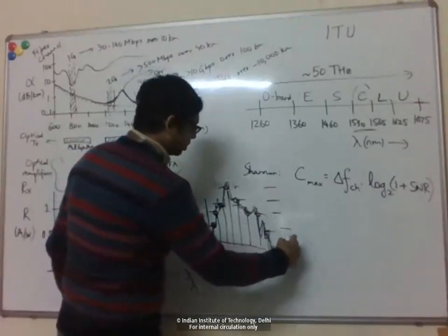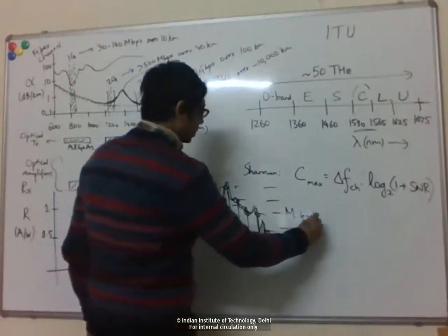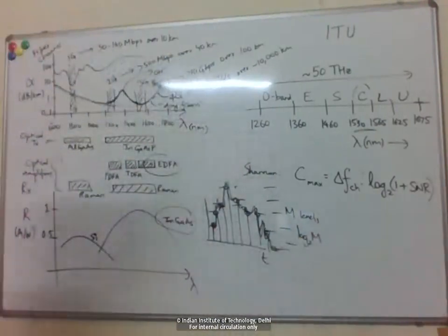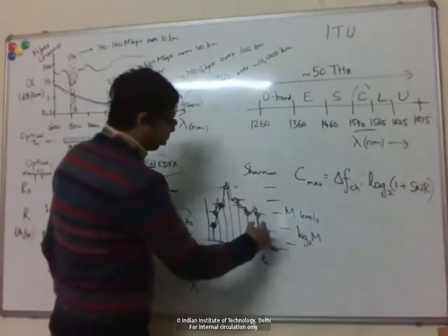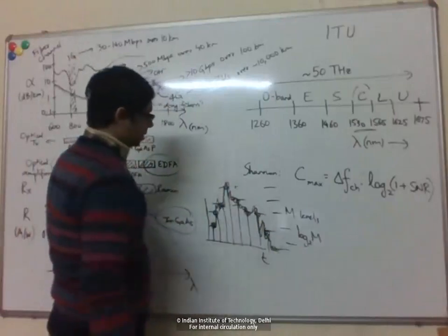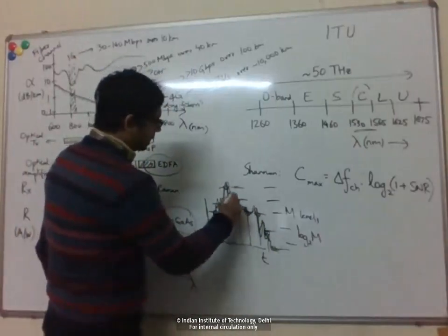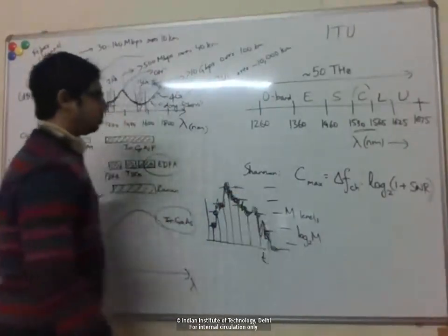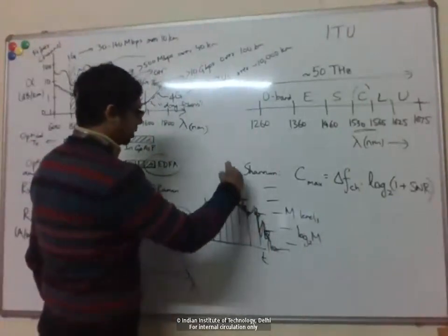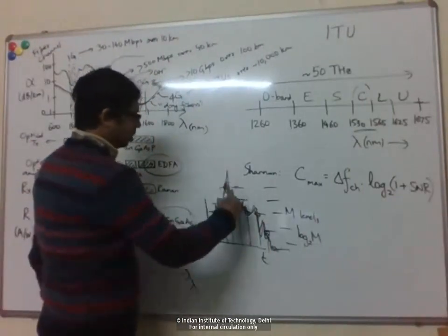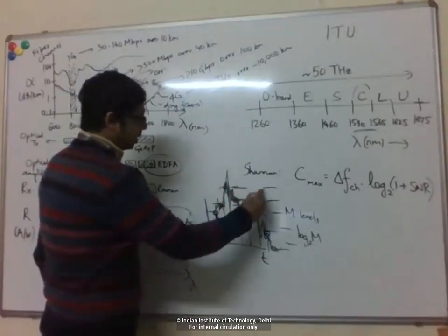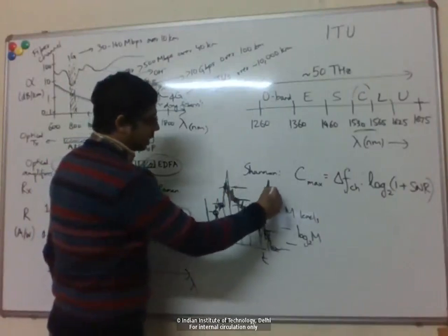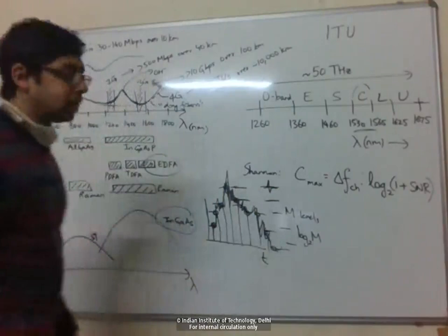So if you quantize over m levels, that is like having log m bits, log m to the base 2 bits, right? And the number of levels you can quantize depends on the noise. The minimum separation between two levels has to be more than the noise, because the signal can fluctuate by an amount proportional to the noise. So that when there is some noise on this, we still quantize at this level, not the next one.